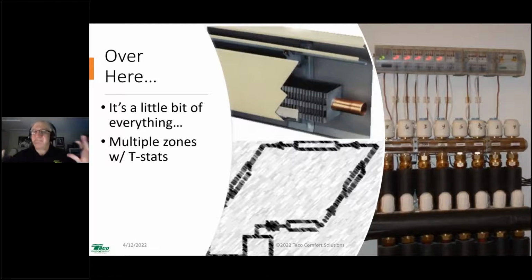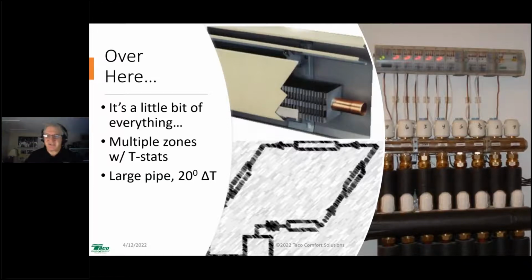So that's why an American style curve tends to be flat. It fits the types of systems we have traditionally installed here in the US. Now that's changing, right? Because we've got a little bit of everything now. But that's kind of the reason a traditional American style circulator will have a flatter curve, like the B&G 100, the Taco 110, the Taco 007: high flow, relatively speaking low head, flat curve circulators, compared to a European style circulator that'll have a steeper curve, lower flow, higher head for those types of applications. So that's why we have the difference.